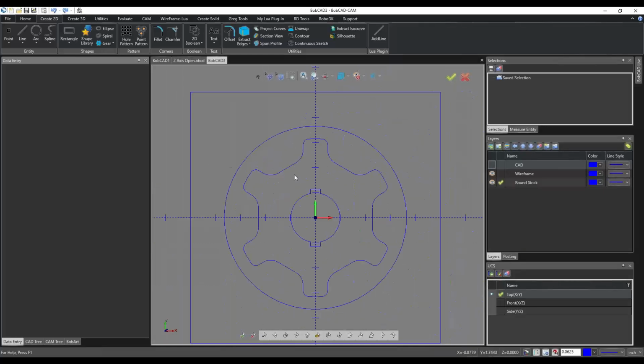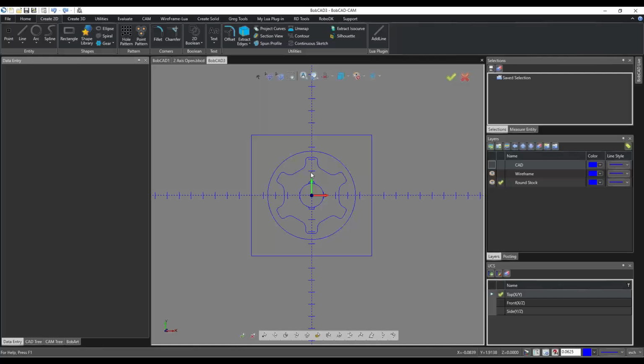So that's basically the geometry selection. Again, there's not too much that you have to do with wire EDM. We just need a wireframe profile of the part, unless you get more into the 4-axis, where you would also want the top and the bottom, and potentially some tilt lines in between. But even that is technically just a wireframe, only in 3D space. So that's basically how that works.